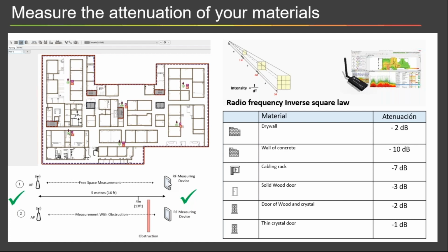And then when I go into Ekahau, you can personalize your walls, and you can say, well, this type of wall has minus 2 dB, this wall of death is minus 35 dB, and then you've got this glass door or this fire door that's like minus 15, and that's going to give you a much more precise prediction, because the values in Ekahau are not random, they're just average values, and they can very well differ from what you're facing. Exactly.